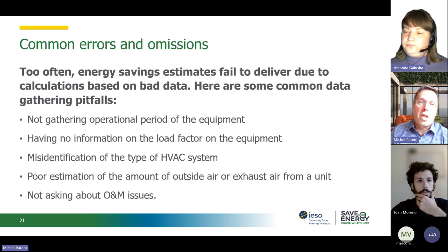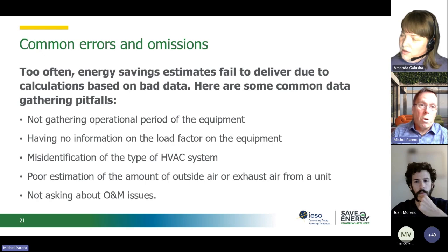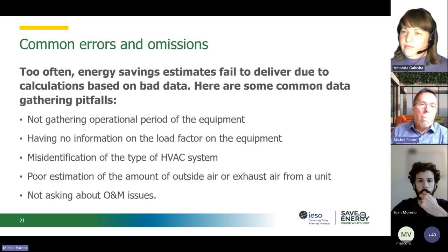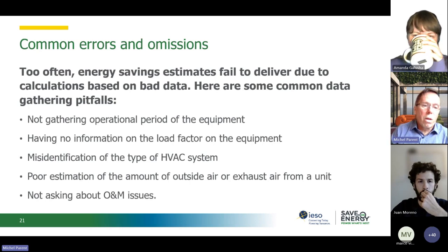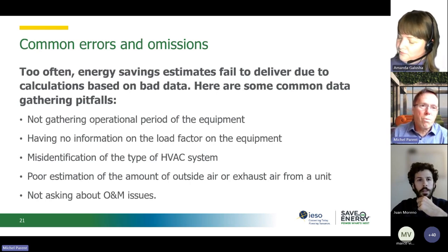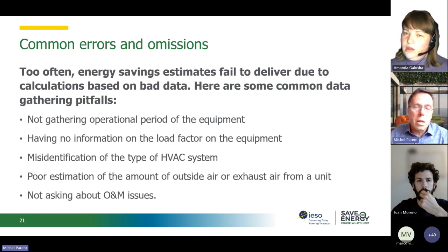And the thermal efficiency in Red Screen, you have to be very careful. When we get nameplate information, it's nominal. It's going to say 80%. Don't ever enter 80% in Red Screen. Red Screen uses that as its annual efficiency. There's no equipment that I know that has an annual efficiency equal to the thermal efficiency. It's always 5 to 10% lower, depending on the quality of your equipment.